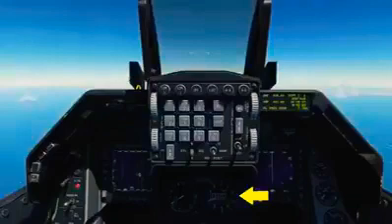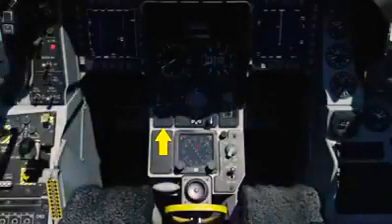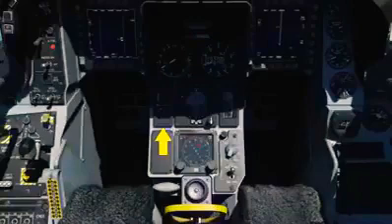The barometric setting allows you to input the desired altitude setting as indicated by the small window to the right of the digital altimeter window. The angle of attack indexer duplicates the same information as on the angle of attack indexer next to the HUD, but it ranges between -32 and +32 degrees. The tape is colored to match the indexer lights next to the HUD. The bar in the center of the tape indicates your current angle of attack in relation to the center of the tape.